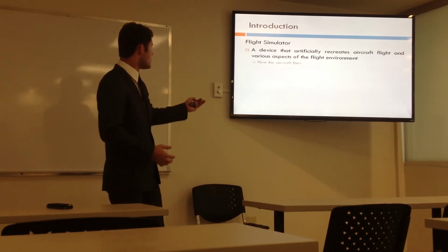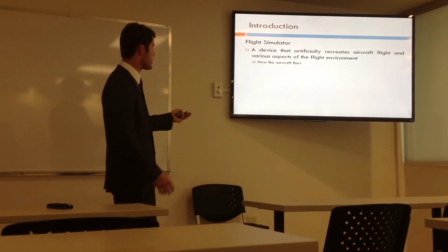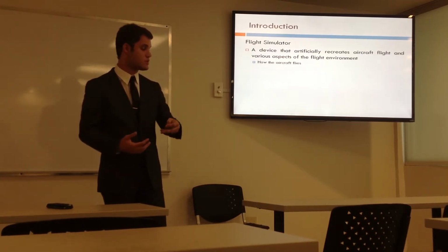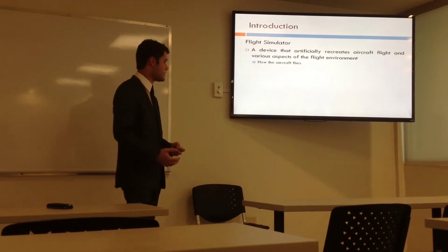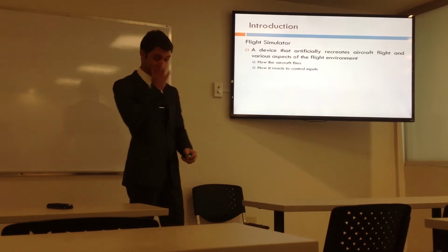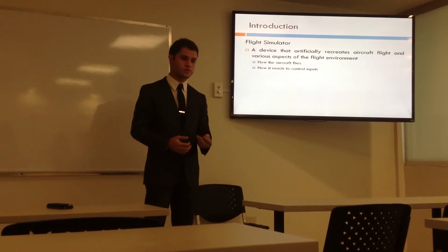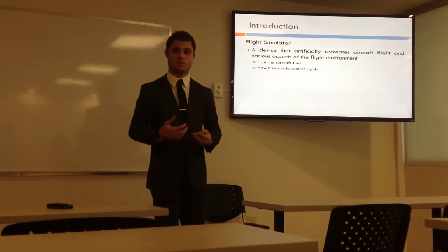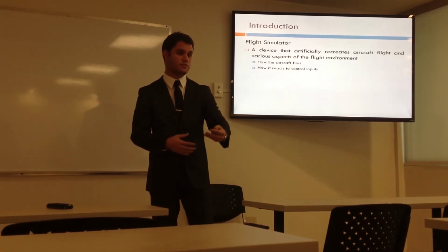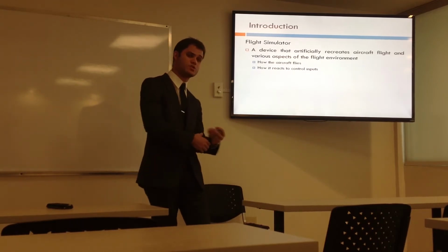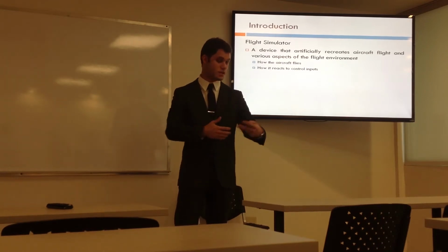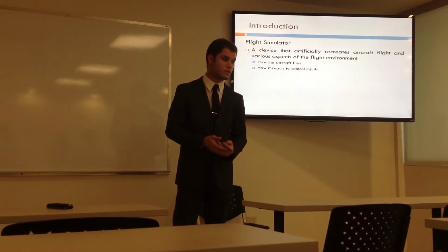So, basically what we're going to measure is how the aircraft flies, its handling characteristics. Is it stable, unstable? Is it agile, slower? What is its takeoff speed? Things like that. The second thing we're going to measure is how it reacts to control inputs. Control inputs being what the pilot puts in the joystick or in the rudder pedals or in the throttle. And to measure how that is going to affect the performance of the aircraft. Because you don't want an aircraft that is too sensitive on the joystick, thereby a pilot accidentally causing a small movement, making a big reaction from the aircraft.